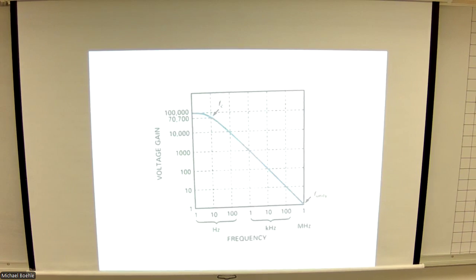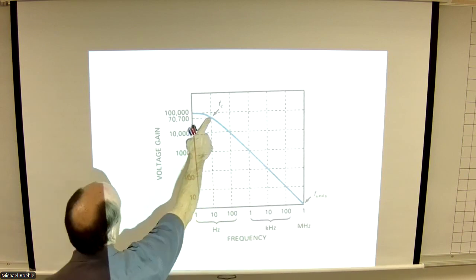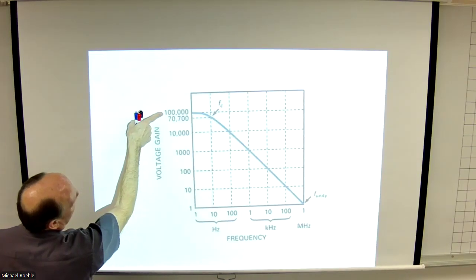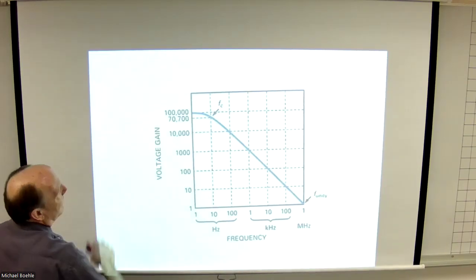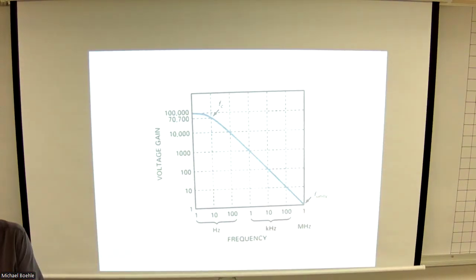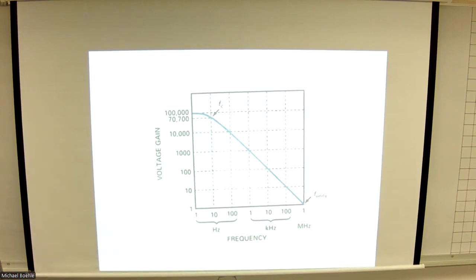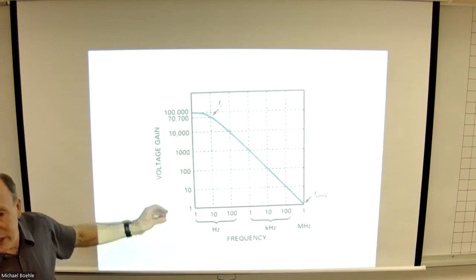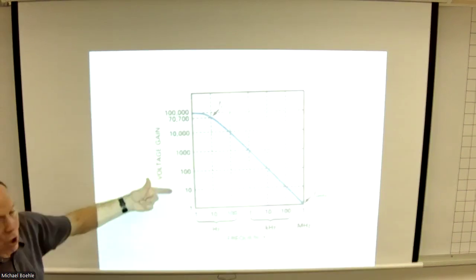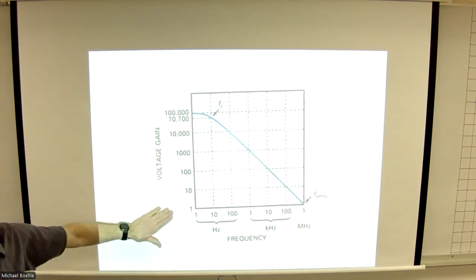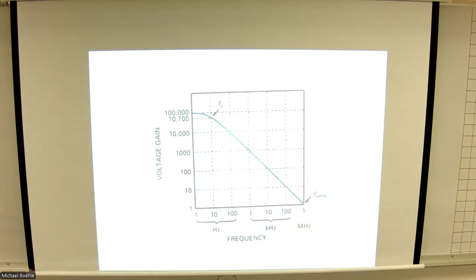There's your voltage gain, right? So this, of course, shows my cutoff frequency at 10 hertz, right? With 100,000, 100 dB, 0.707, of course. Yeah, so unity gain frequency, right there, 1 meg. Now, this looks like a real Bode plot because of the curvature here. But notice that this is, of course, a log scale. Instead of decibels, this is also a log scale, which when you have linear decibels, that's the same as a log. So that's why the shape is the same. All right.